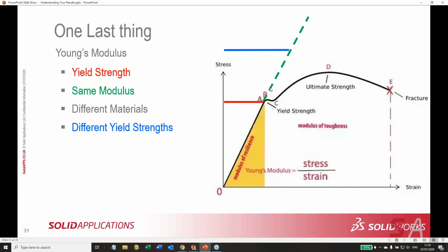Okay, so I want you to know that you can change material to something 3 times as strong with the same stiffness, basically, the same modulus, and you're going to get the exact same plot, except you'll know that your results are under yield, and therefore they're extremely accurate there. Okay, so that's a kind of a caveat about what a FEA linear static analysis does.